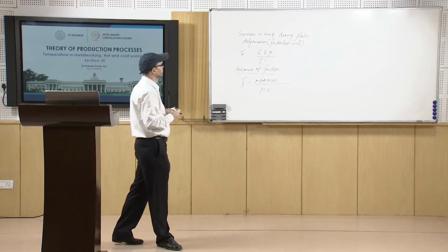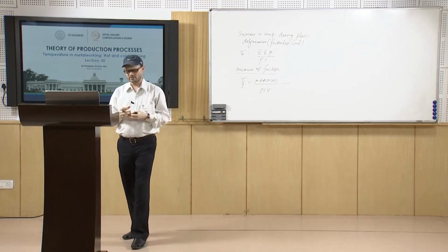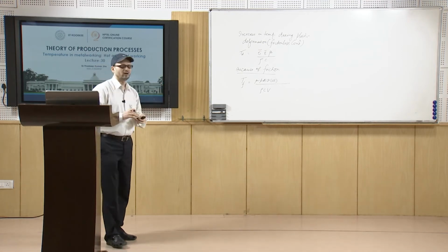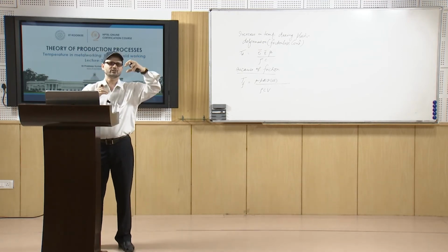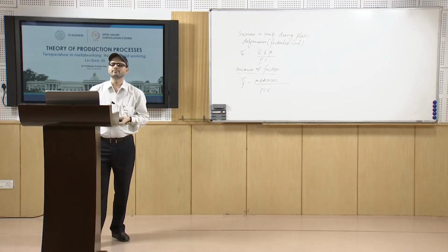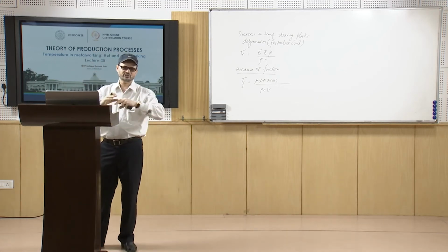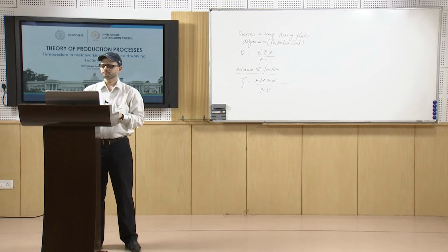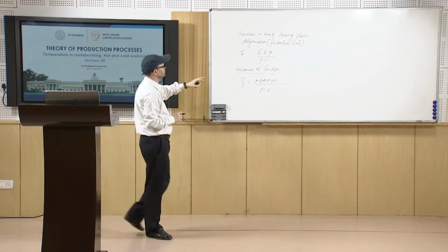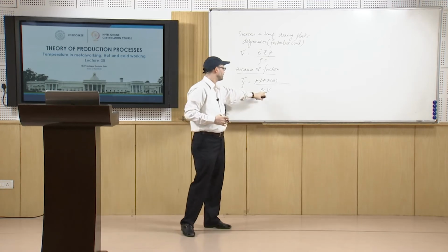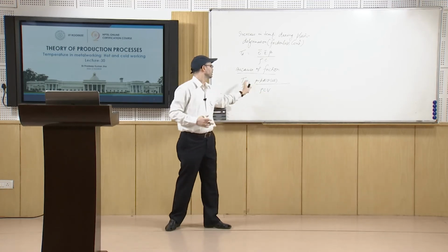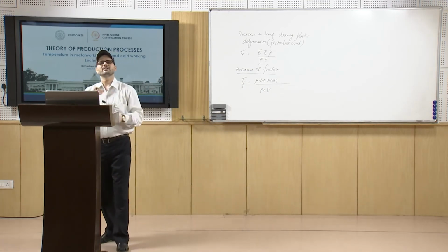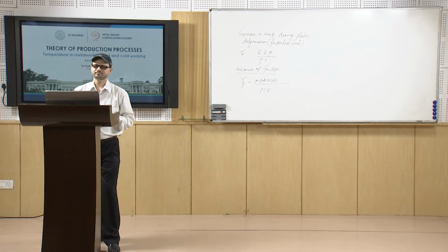So, when you go for deformation, you need to know some of the things, which are quite simple. P will be the stress normal to the interface, and A is the surface area at the interface. So, you have these terminologies which are very common, and V will be the volume of the material which is subjected to temperature rise. So, you see this expression talks about the increase in temperature because of the friction. So, that is how you calculate it.